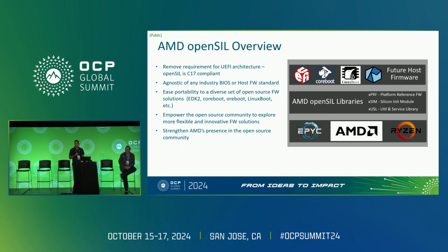It stands for Open Silicon Initialization Libraries. The UEFI requirement is removed. It's written in standard C, and it's agnostic of any currently architected host firmware standard. So we would want a UEFI EDK2 solution to be able to interface directly with it, a coreboot or U-Boot, or any other firmware architecture to call these libraries directly.